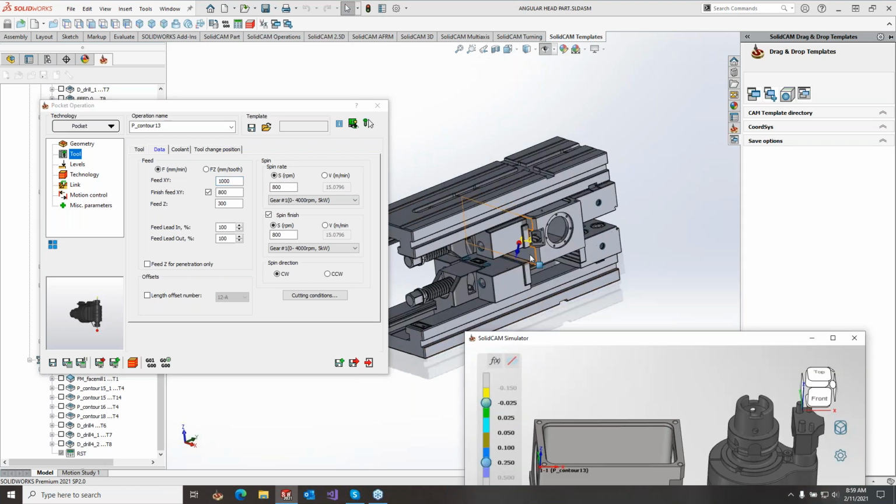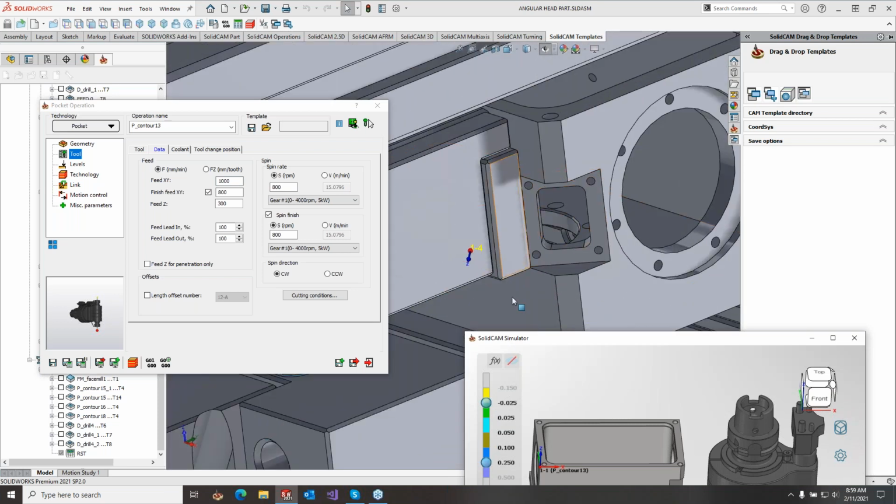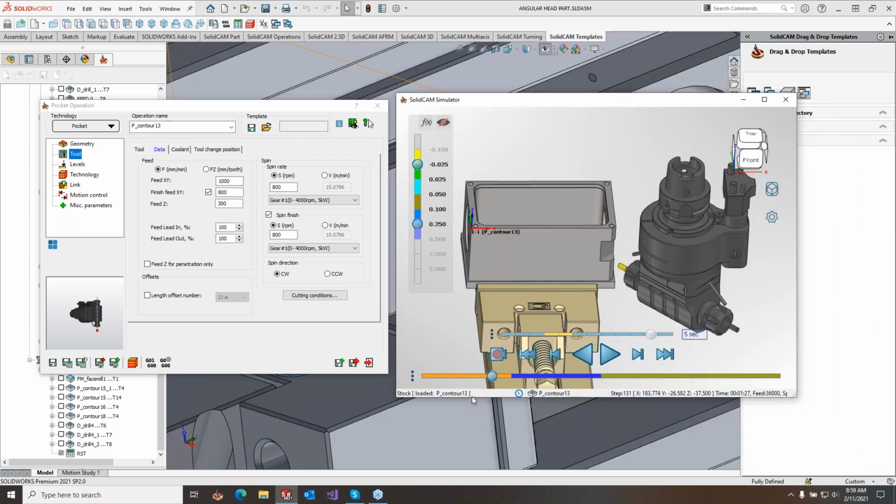It's not doing a tremendous amount of toolpath, just some facing, and that operation takes exactly 1 minute and 57 seconds. So the simulation is played in exactly 1 minute and 57 seconds if you're on machining time mode at 1 time speed. And if that is too long, if you change this to a 2 times factor, it will play in half of that, roughly 58 seconds.